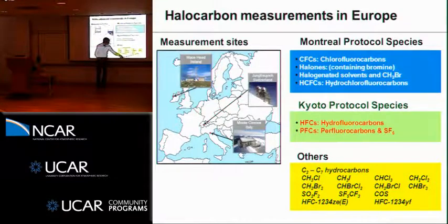This is a very interesting species. For instance, this is a hydrofluoroolefin. So it has a double bond and is also shorter lived, only a few days. And this has been suggested by the industry to be used in all the car air conditioning systems to replace HFC-134a, which is used today. But there are only a few models in the US which are using this so far. There's a big debate about the species, especially the safety in the cars. Daimler-Benz doesn't want to introduce it. So it should be used in all new models, also in Europe, but it isn't.